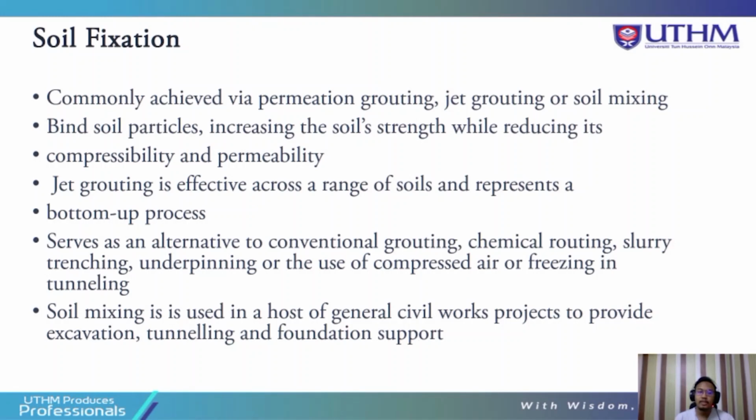Jet grouting is effective across a range of soils and represents a bottom-up process. This technique serves as an alternative to conventional grouting, chemical grouting, slurry trenching, underpinning, or the use of compressed air or freezing in tunneling. It is commonly used to provide excavation support of an existing structure before an adjacent site is excavated to make way for a new deeper structure.